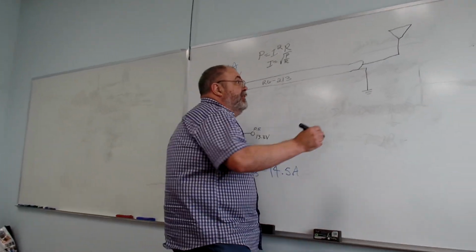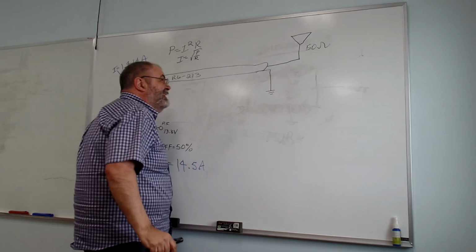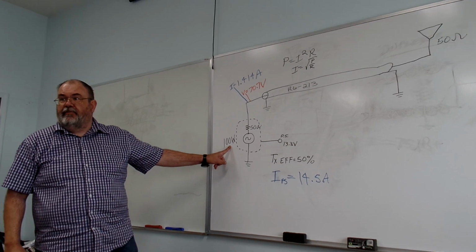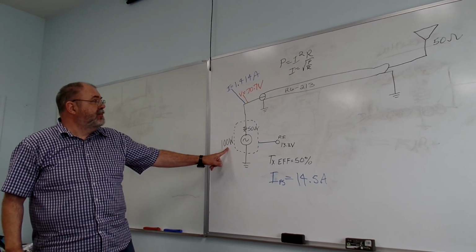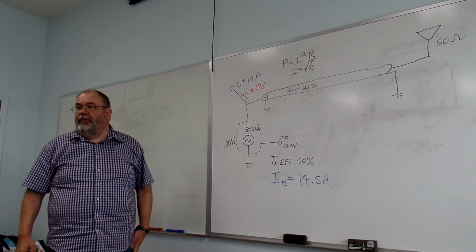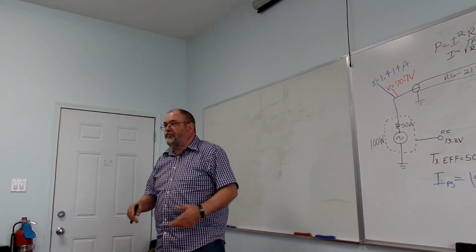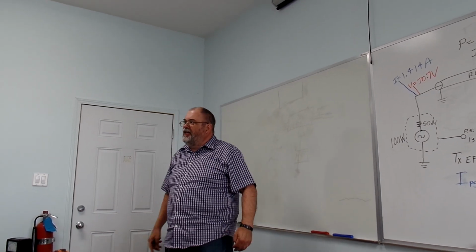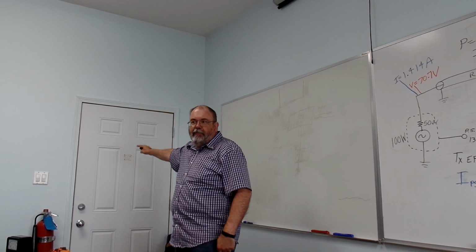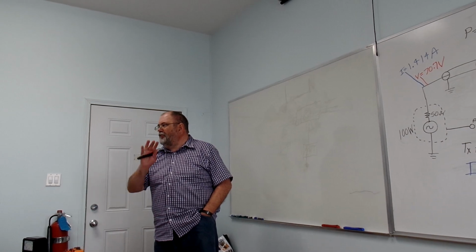Okay? So if our antenna here is a 50 ohm match, question: which P is that there in I? 100 watts. So it's 100 divided by 50, which is 2. The I is the square root of 2, which is 1.414 last time I checked. It's actually more digits than that, but it's one of those numbers that goes on forever. We have a little rounding error, close enough.